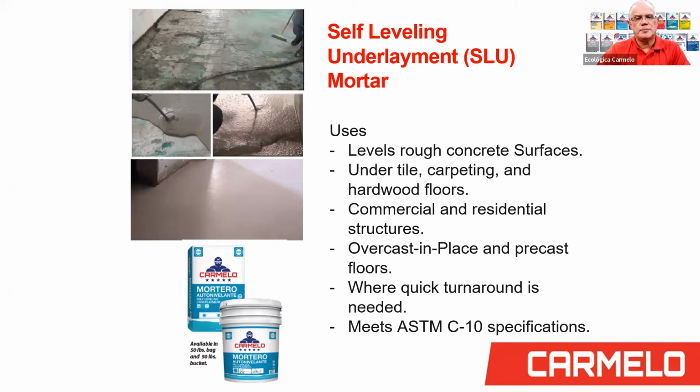You can also do some testing, making sure the vapor drive in that slab is not higher than 4 pounds with a calcium chloride test. Or if you're measuring RH, relative humidity, with an in situ test, where they make borings and then check the humidity, the relative humidity shouldn't be over 75%.